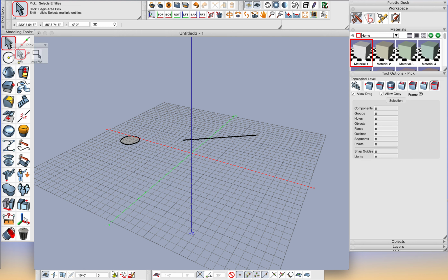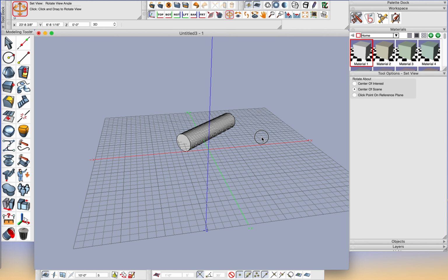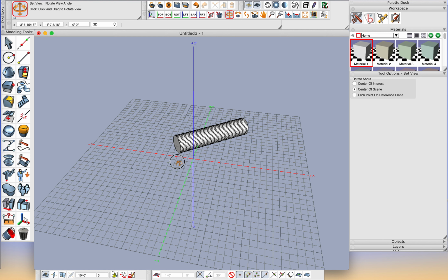When I click on my Axial Sweep tool, I first select my source shape and then the path itself. The software has taken that initial 2D shape and created a 3D object along the pathway that I drew. In this case, it's essentially just a long cylinder, which is pretty easy to make.